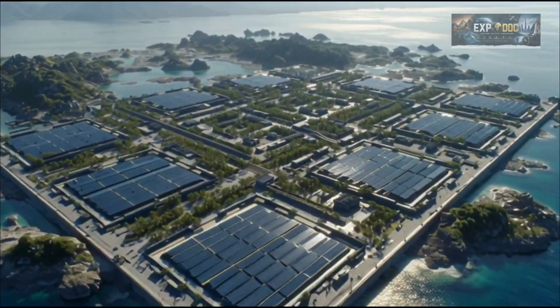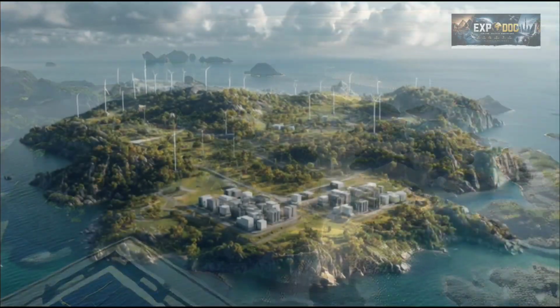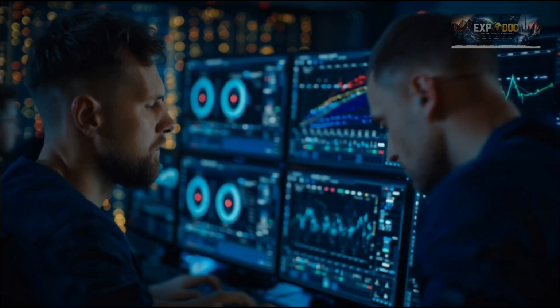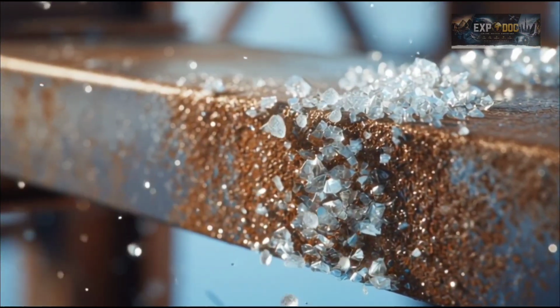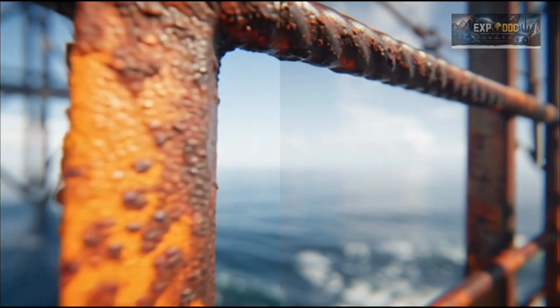Engineers also place special emphasis on protecting structures from corrosion. Salt carried by the sea dramatically accelerates the deterioration of both steel and concrete. To combat this, builders use specially formulated marine-grade concrete with enhanced resistance to salt water, while steel components are coated with multiple layers of high-performance anti-corrosion protection.